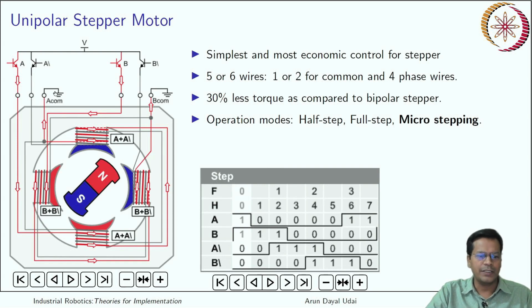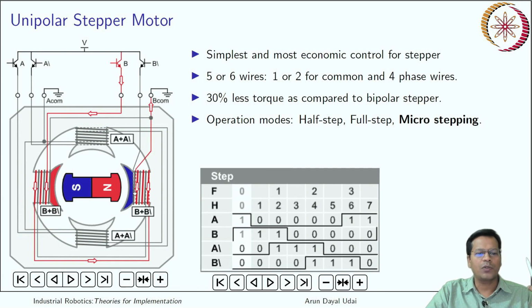So yes, now let us see how it works. Let us say your motor has started already. Okay, it is here in this position. What you see, the blue one, if I say, is the south pole. The blue one is the south pole which is attracting the north pole of the armature. The armature is at an angle now. So when both the poles are high, the armature goes to this particular position. This is a magnet which gets attracted towards the pole which is high. Okay, in the next position you will see only one of the poles is high, and the other one becomes opposite to that.